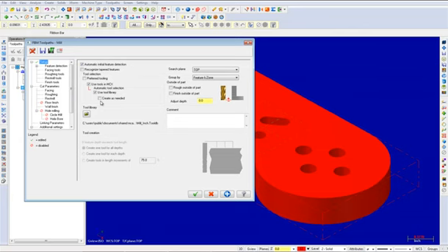Automatic initial hole feature detection is where Mastercam automatically detects features when you choose the FBM operation. If you save the settings to your toolpath defaults file, and use that file in the active machine group, Mastercam automatically detects features every time you choose the FBM operation. Recognize tapered features allows wall and boss features with consistent tapers to be machined.